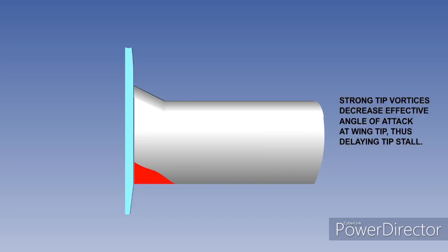On a rectangular wing, separation tends to start at the wing root trailing edge and spread forward and out towards the tip. Since the reduction in lift occurs initially inboard near the C of G, even if it happens on one wing slightly before the other, there is little tendency for the aircraft to roll. The aircraft loses height, but remains more or less wings level.